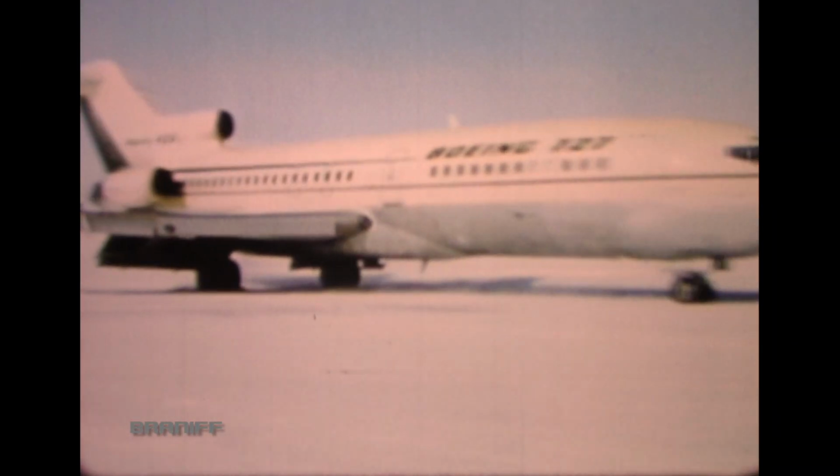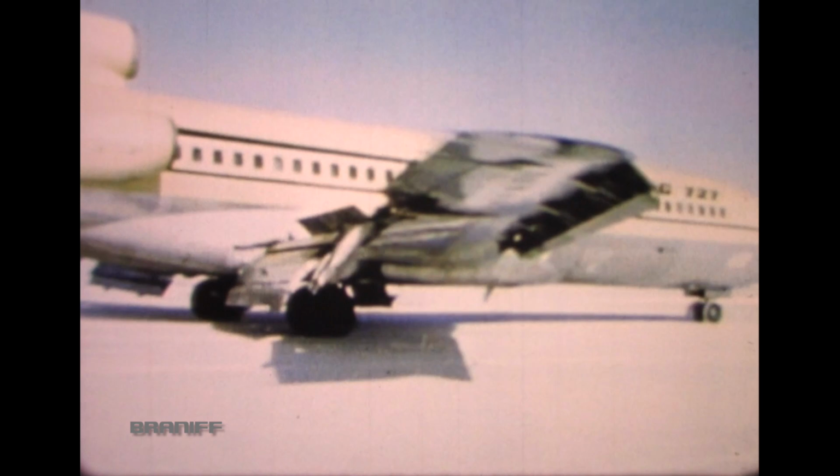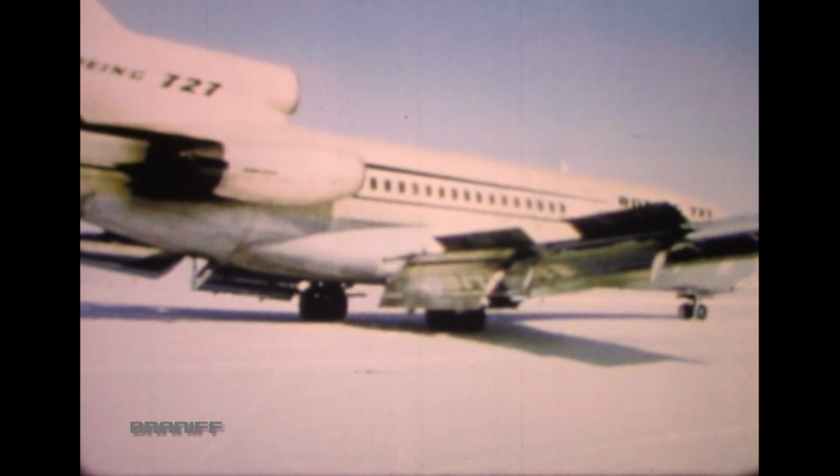Finally, do not attempt to turn off the runway until speed is reduced to a safe level. Turns onto icy taxiways, combined with high taxi speeds, can cause skids. During taxi-in on snow or ice-covered surfaces, some similar ground operating procedures apply as when taxiing out.